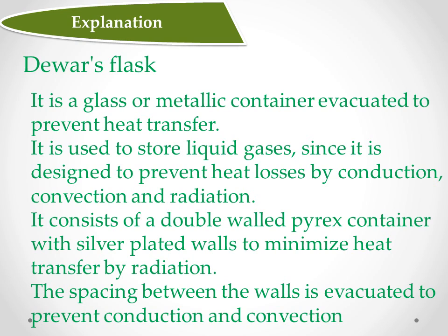It consists of a double-walled Pyrex container, with silver-plated walls, to minimize heat transfer by radiation. The spacing between the walls is evacuated, to prevent conduction and convection.